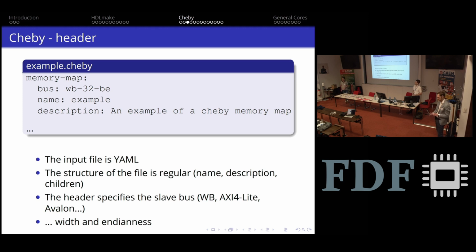So we had to disable this feature inside the transceiver. We don't enable bit sliding, and then we do it manually, where we know exactly how many cycles we spend gathering bits. It's a different layer. There is a part which depends on the transceiver we are using.